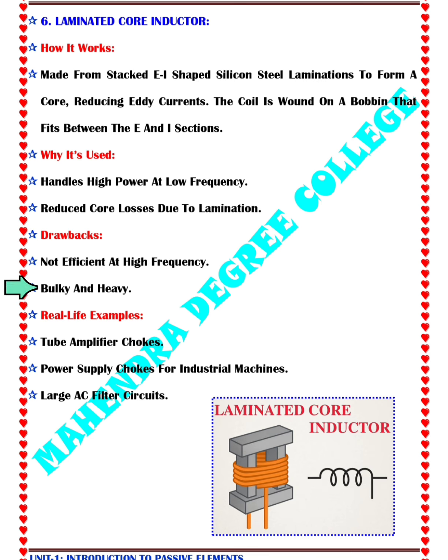Bulky and heavy. It means to handle high power and reduce losses, laminated cores require thick or large stacks of steel sheets. This makes the component physically large and heavy, which is a disadvantage in compact electronic devices.